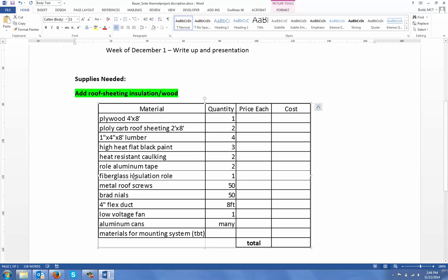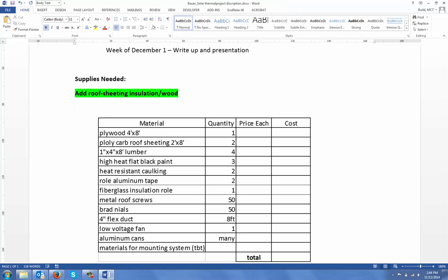Tim had some nice fiberglass insulation. They make insulation just for that duct. It has a foil exterior. Right. And it's designed so you just wrap it around and run a duct tape seam on it. Works great. Okay, I'll just put that on there, foil backed.